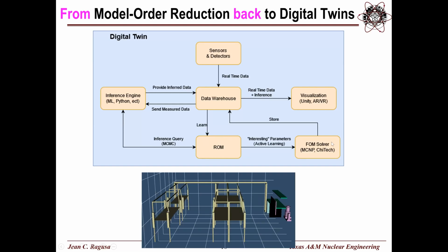The reduced order model is, of course, built on full simulation models that we've done offline. So we've learned the active subspace in which the parametric solution lives, and the inference engine therefore only needs to use a reduced order model. There may be other additional functionalities, like if the inference engine is having troubles, you can always request the full order model, let's say overnight or over the weekend, to generate a few more snapshots to help clear out some issues.